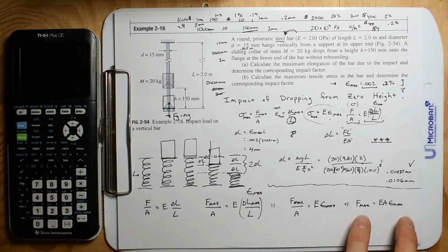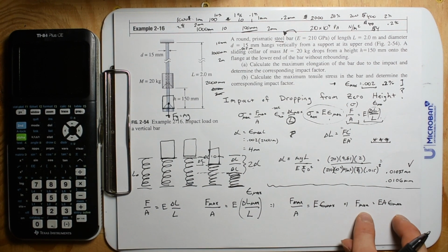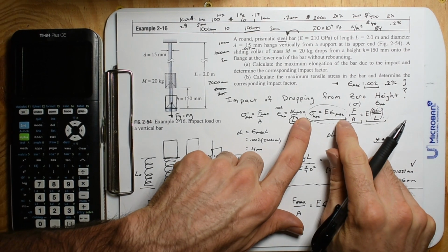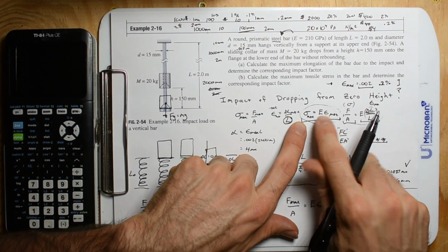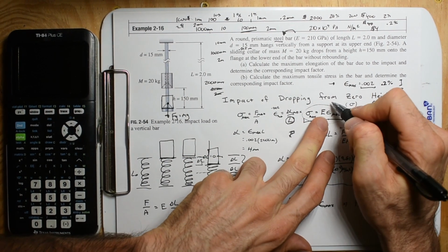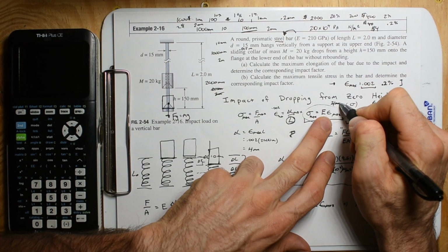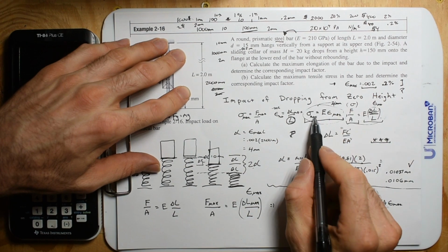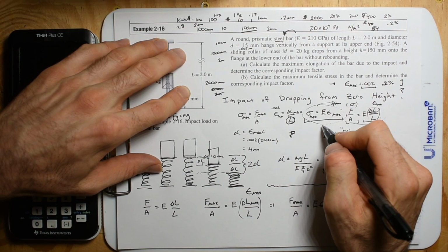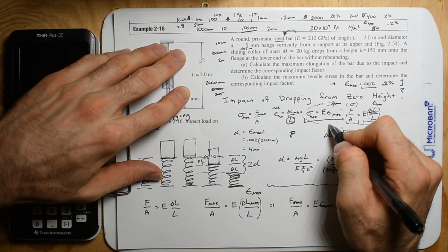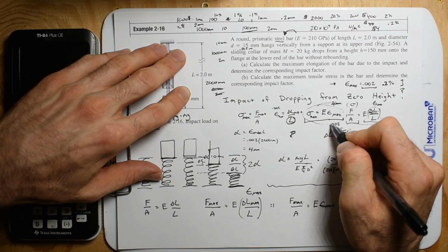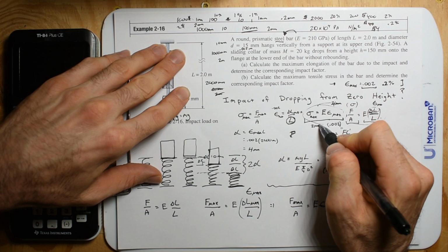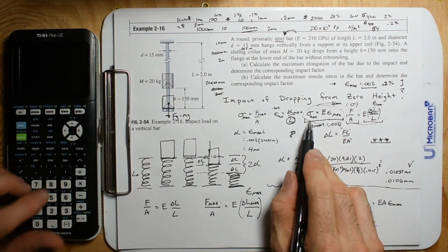But even right here, I think we've lost all touch from the problem. So this equation is kind of the gold. What this says, with the modulus of elasticity, is if you have 4 millimeters for our scenario, we are going to generate a max. And the max strain for this is 0.002. So we're just going to take 0.002 times 210 times 10 to the 9. That is going to give us the max stress.